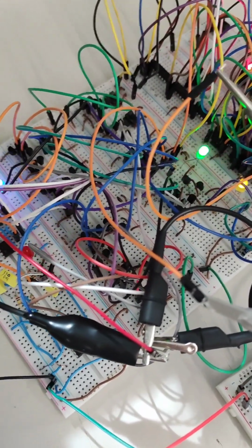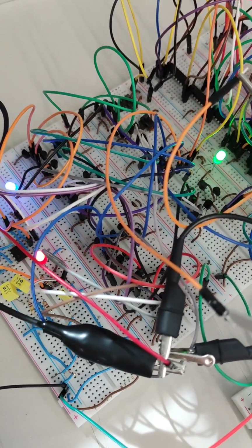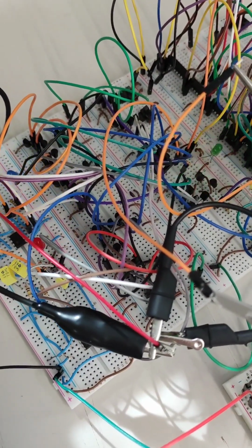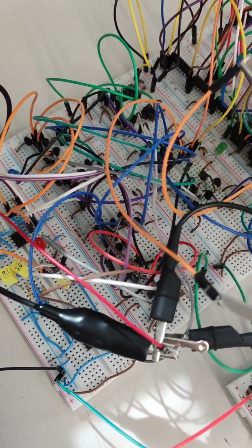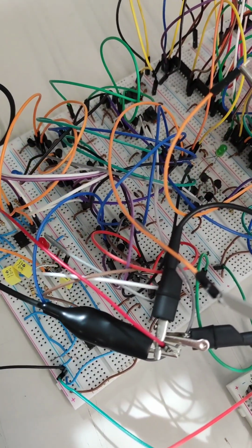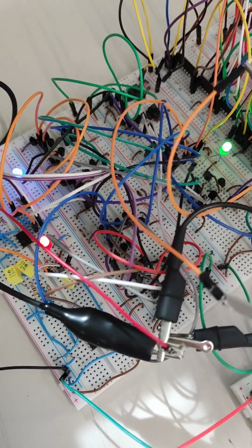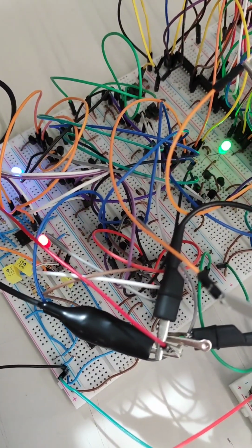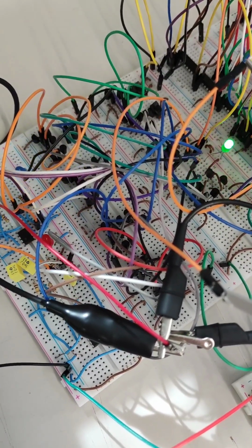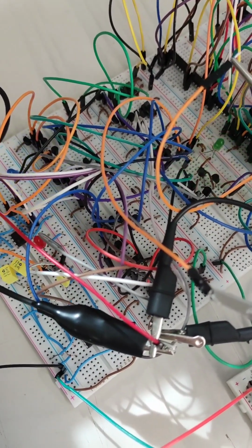Now secondly, I will explain the second task of the project, the 2x2 multiplexer circuit. We set up this circuit with transistors. Before setting up this circuit, we used the K-maps that were also included in the final report. In these K-maps, we obtained the Boolean expressions for B0 and B1. Then we obtained the simplest form of these expressions. Then according to these Boolean expressions, we set up the multiplexer circuit as seen.